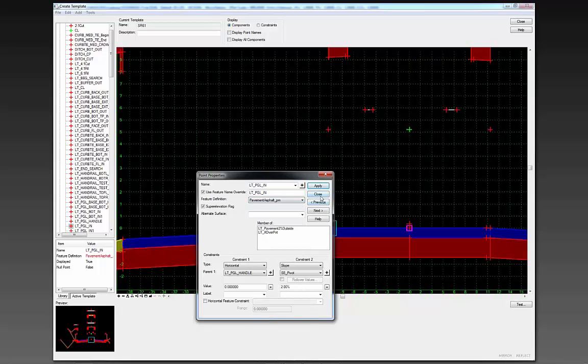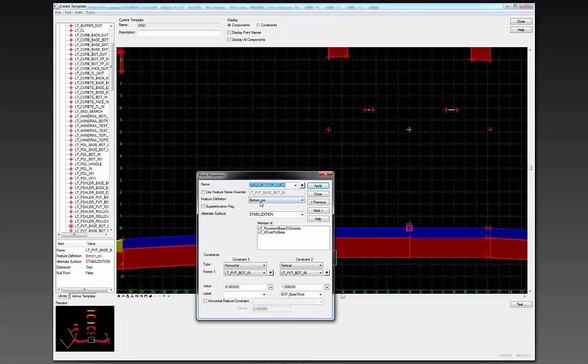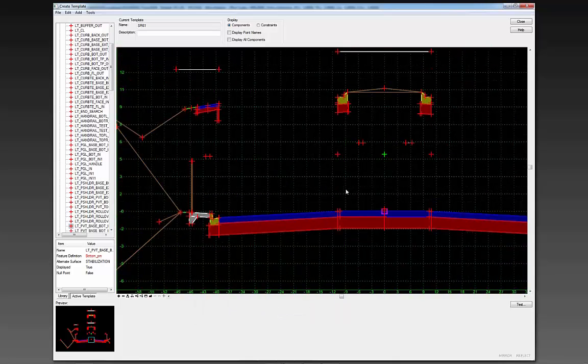That's the one thing. The other thing is that at the bottom of these are all going to be bottom PMs, so anything below the surface is a bottom PM. The reason we did it that way is because the contractors that we spoke with in the construction industry, as a rule, will take the proposed surface, because that's all they've ever been given in the past and what they usually get from cross sections, and create a proposed DTM that they use in their software. Everything that they lay out is going to be depth based from there.